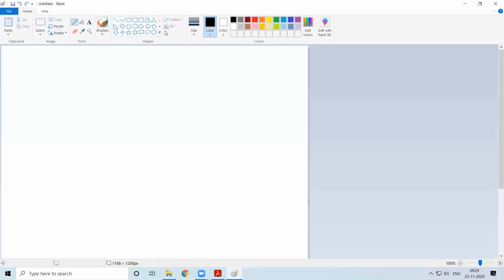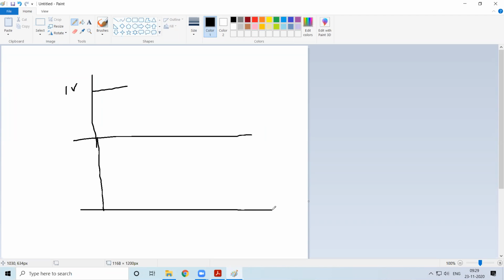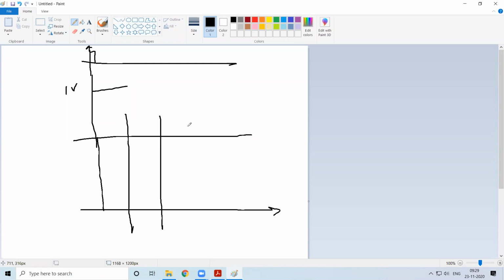in simple terms, say for example, I have a signal, say this is 1 volt, and there is a pulse of some width. So this is the pulse. In a given time period, the position of the pulse decides what its amplitude is. That is, you are modulating the position of this pulse and nothing else you are altering. The characteristic modified for this pulse is its position.